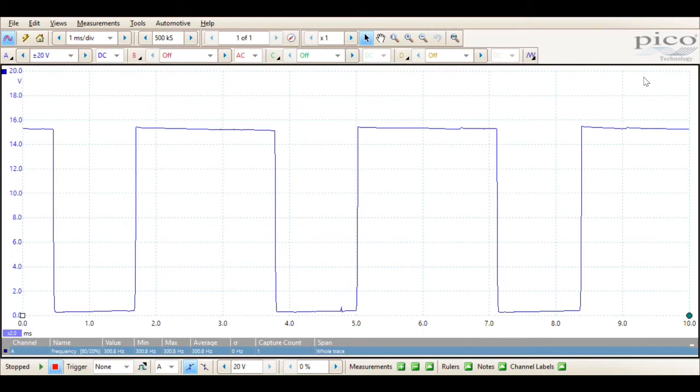Now we're going to discuss the term duty cycle. Duty cycle is a measurement of on time versus off time, and it is measured in percent. Okay, so it's not time like pulse width was, it's percent. And you're often going to see duty cycle interchangeable with the term pulse width modulation. So pulse width modulation is when the computer is changing this on versus off time in order to control the amount of current going to a specific component. And by controlling the amount of current, we can control things like fuel pressure in a fuel pump, or how far a solenoid opens, or the dimness of a bulb, those kinds of things.